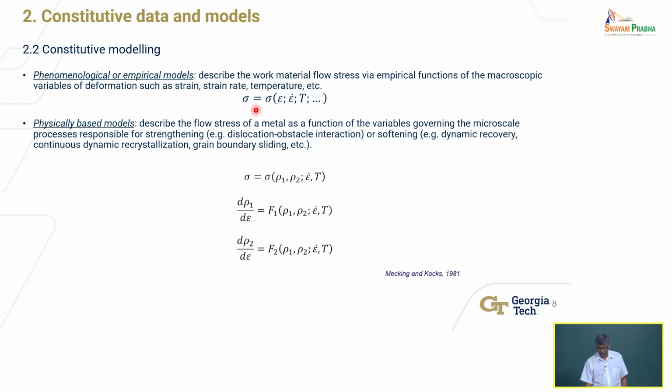So just be able to say, you're all familiar with stress as a function of strain. You all know in elasticity, Hooke's law, right? At least you know that. So Hooke's law, sigma equals modulus of elasticity times the strain. Well, this is a generalization of it, where sigma is equal to some function of not only strain, but also strain rate and temperature, because the material is being deformed at very high rates or at different rates and at some other temperatures than room temperature.